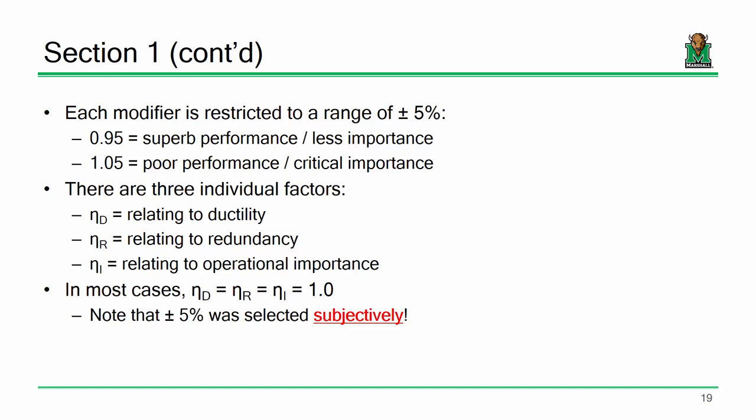And I'll give you a really simple example. The bridges that we focus on in here are composite steel girder bridges, slab on steel beams. Now, in America, a very common layout would be maybe 4 beams or 5 beams, or if you've got really wide bridges, you use more than that. Very rarely in America would you see a 3 girder bridge currently constructed, and you'd almost never see a 2 girder bridge constructed for a number of reasons.